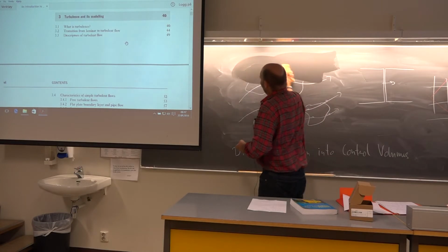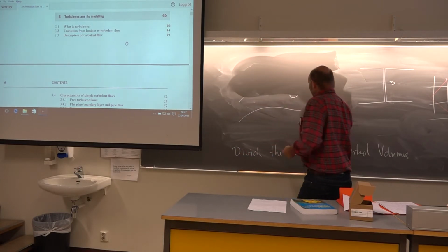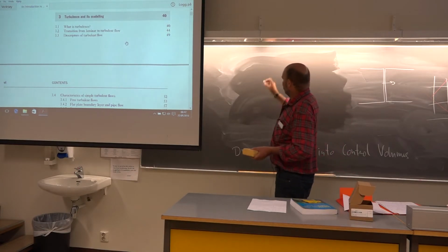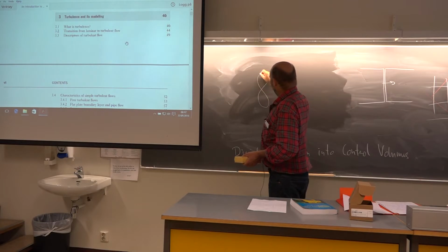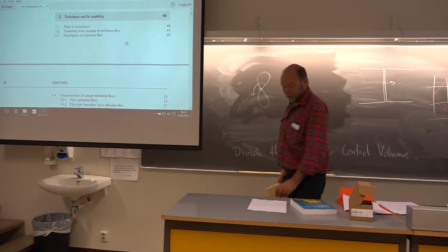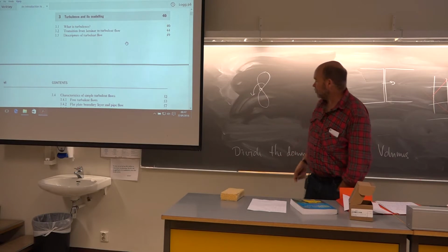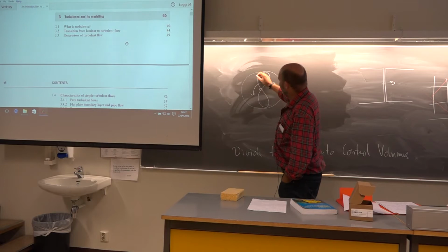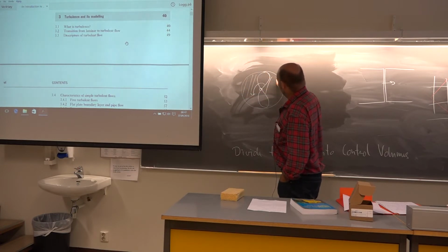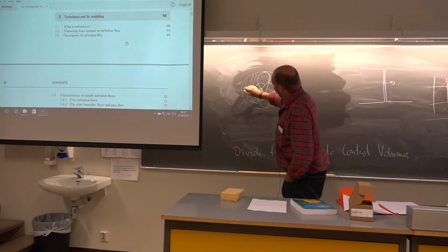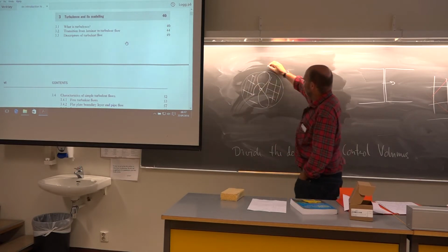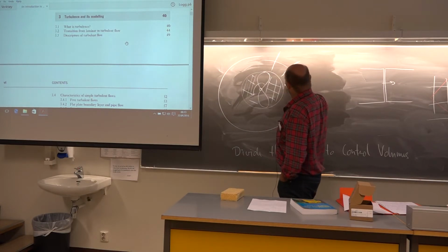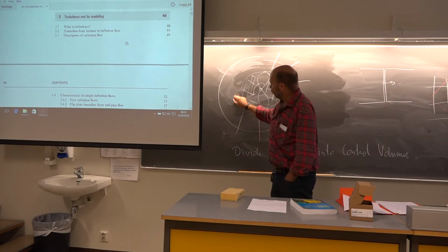With moving meshes, that is typically when you have, say, a moving part. You want to simulate the flow around, say, a propeller. It rotates. How do you do that? Well, you construct one mesh that is circular. So here you have some mesh system around the propeller, and then outside here you have a steady mesh that doesn't move.